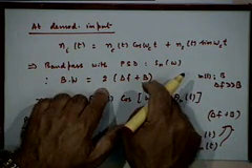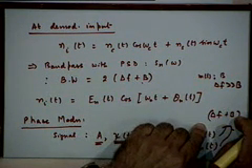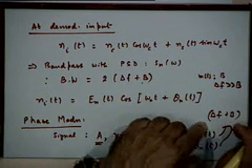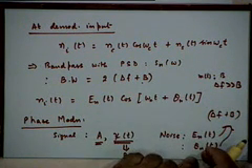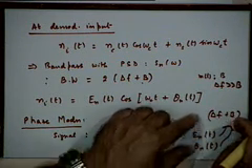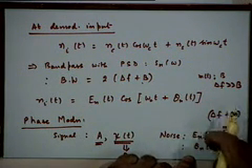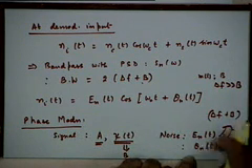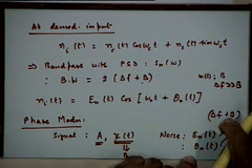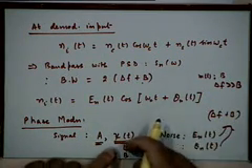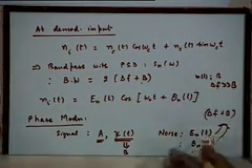The band pass signal had this bandwidth, so the corresponding two low pass signals will have this bandwidth, right? n_c(t) is e_n(t) cosine theta_n(t) and n_s(t) is e_n(t) sin theta_n(t). So the envelope and the phase of the noise will fluctuate much more rapidly than the phase of the signal containing your intelligence.